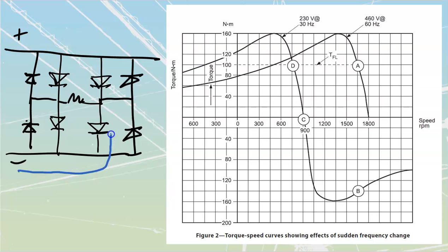coming from usually our inductor collapsing field or a cap. Remember the VSI and the CSI types of drives are going to be filtering, meaning we're rectifying in, but then we're storing some energy inside of that cap and that inductor to give us that ride through. So normally I'm going to have current that's going to be going through like that.